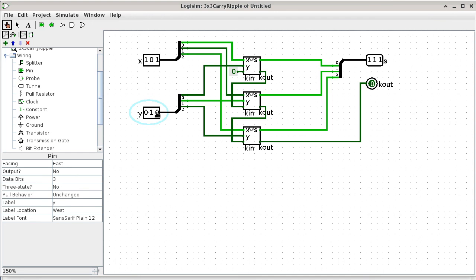So let's say Intel looks at this and goes, this is simple, we like this. And then AMD comes up with a better approach, which is called the carry look-ahead mechanism. Then Intel cannot do this anymore. So even though this approach is very simple, and it doesn't use a lot of gates, we cannot use this. I would not be surprised if you move on to a 4-year university in computer architecture or logic design, they talk about adders and this is what they tell you, because it's easy, it corresponds to the equations, but it has this fatal flaw of taking a long time to compute when adding 64 bits.